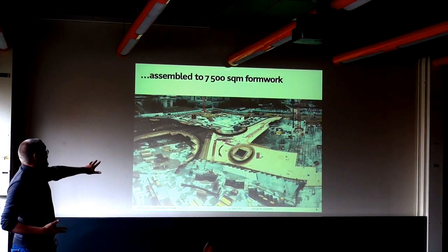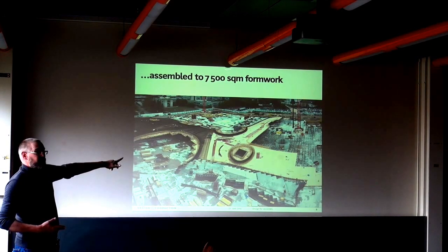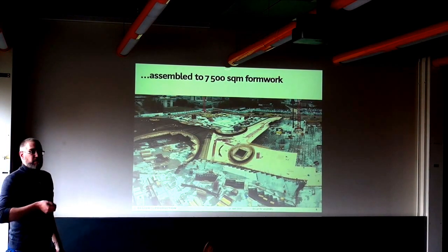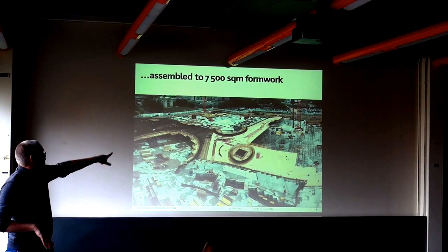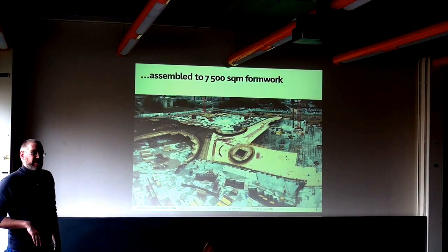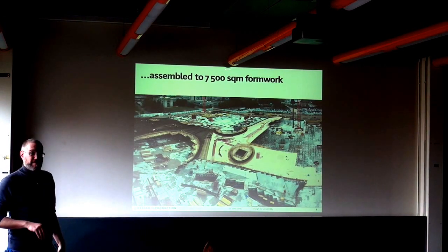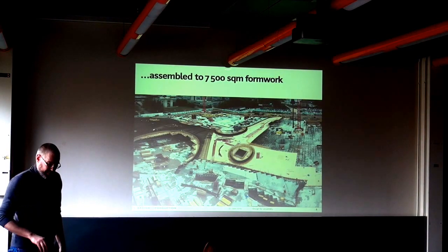This is where you can see the whole area. On the right-hand side, there's still the scaffolding towers, adjusted to within 2 or 3 millimeters height where they should be. Then the boxes are put on top of them, and on the right side there's already the rebars in there, the reinforcement for the concrete. And as you can see, there's pretty much steel in this concrete slab. Remember the next time when you walk on that.